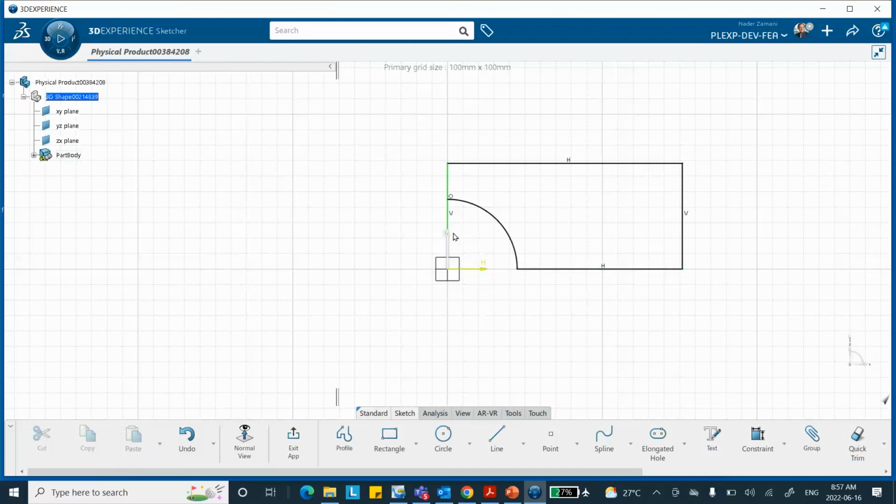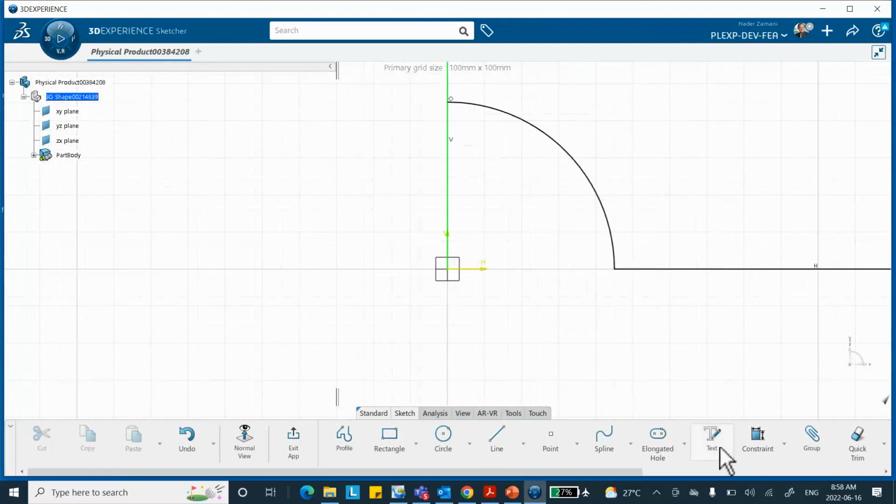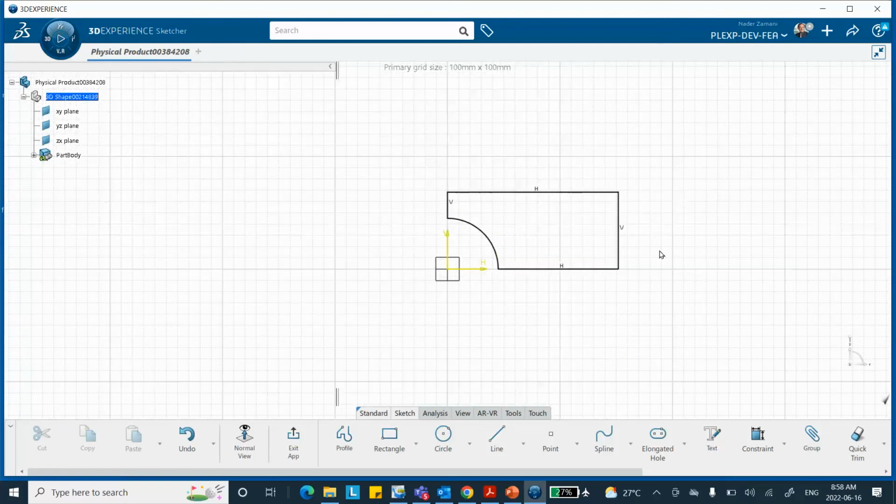There. I was taking the axis. What do I have here? Why is it not taking that? Yeah, good. Because I clicked on it once. When you click on it once, even Catia closes that quick trim. If you click on it multiple times, you can select multiple lines. That's what happened. Good. Exit.